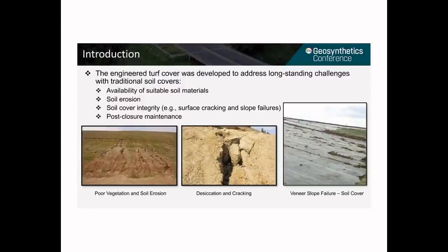Traditionally, landfills have been closed with soil covers. The engineered turf cover was developed to address long-standing challenges with traditional soil covers, a few of which are listed here. First, soil covers need soils. Some sites may not have enough soils available, or they have soils, but the soils may not be suitable and do not meet technical requirements.